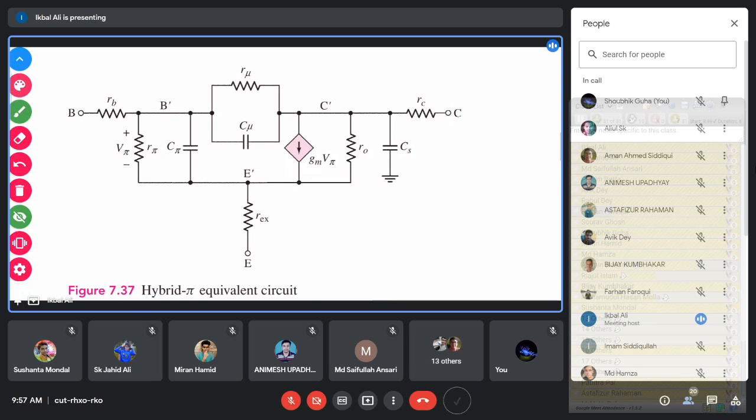The simplification is this RB resistance, the n-type base material resistance, which is very small, 1 ohm, 2 ohm, very close to 0 ohm. So this resistance you can treat as a short circuit, very low resistance. You can assume that RB is a zero resistance.